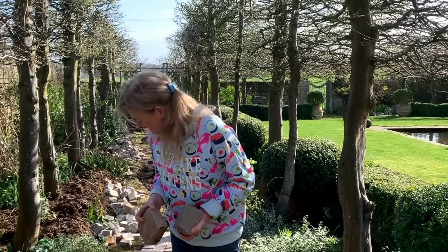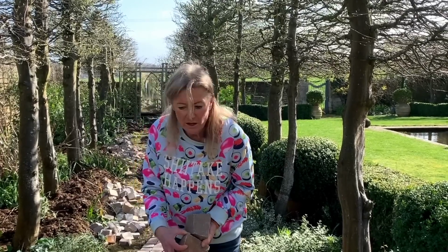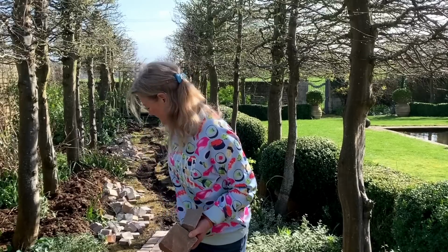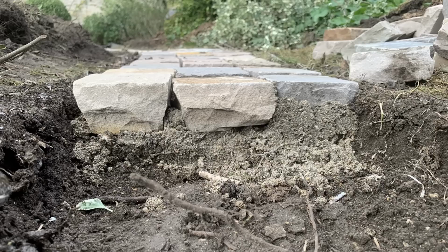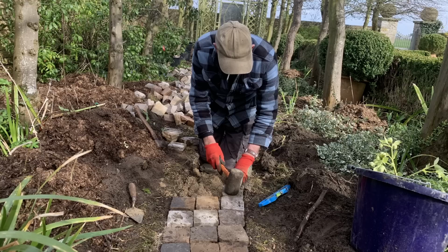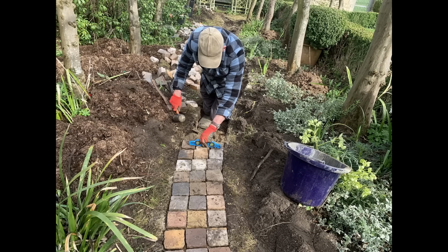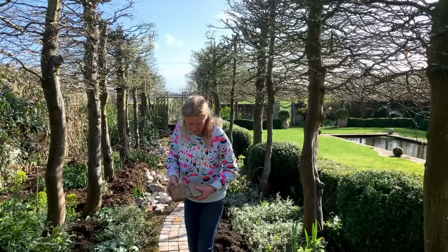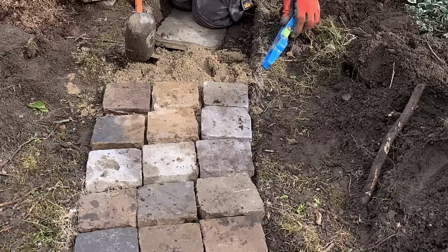But what happens is, Dave will put the mixture of sand and cement here. It's a sharp sand. He'll lay a bed to a depth of about 50-60 mil, and he'll push them in, and he'll choose the ones of a similar depth as he goes. So he'll have an area all quite thin ones and then all quite fat ones,